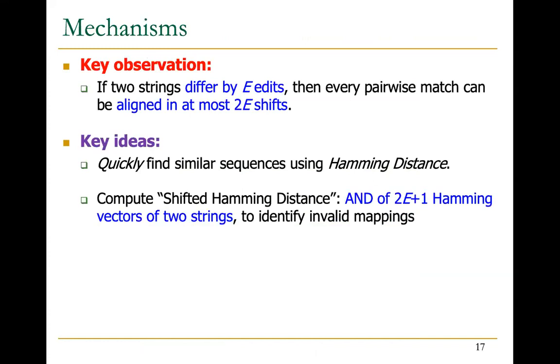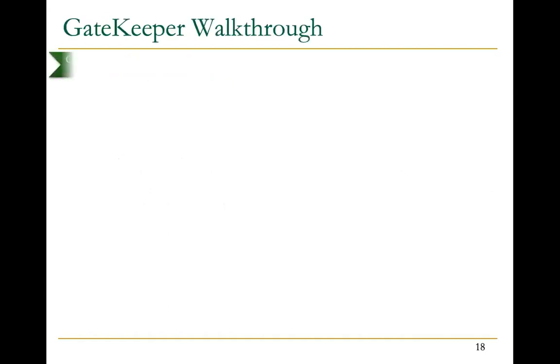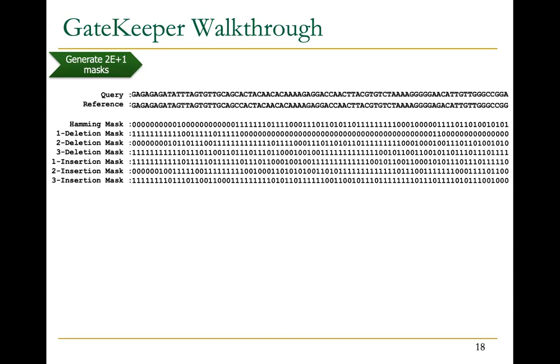All right, so that is the algorithm. And now for the implementation, or how we really implement it on FPGA or on logic gates. So first, let's see a real example with real data. This is the real sequences from human genome. What we need to do is the Hamming distance calculation, just XOR between the 2 sequences. You can see it's 0 where they exactly match, 1 where they don't match in the corresponding locations.